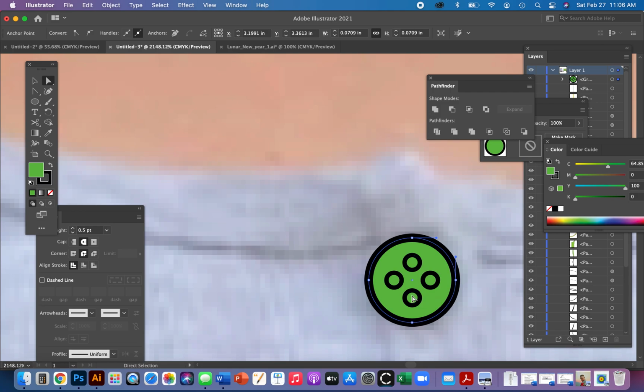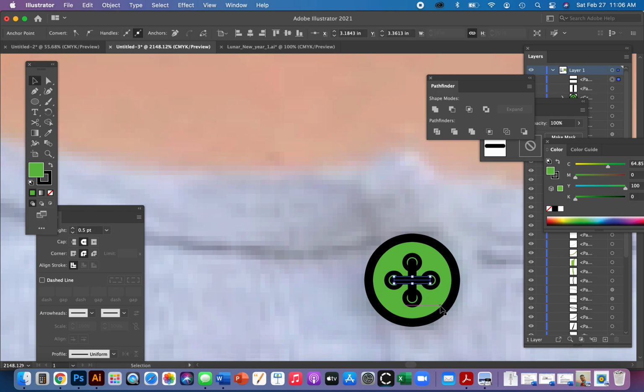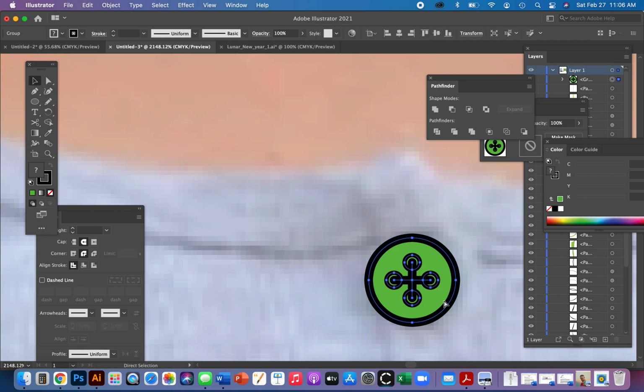Do you want to put thread in there? That might be too much. You can if you want. I'm gonna hit letter P. This might be overboard, but there's your thread in case you want it. Hit the letter V. I'm gonna hold Shift, and then I'm just gonna group it all together.